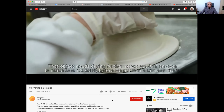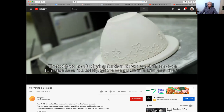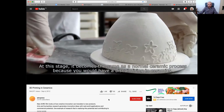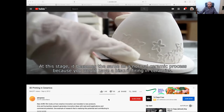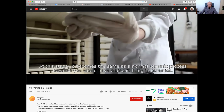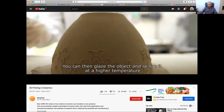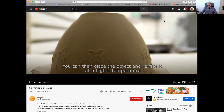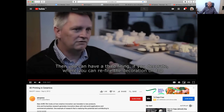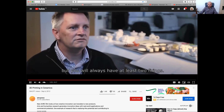That object needs drying further, so we put it in an oven to make sure it's really quite solid, before we then put it into a kiln and fire it. That's known as a biscuit firing, the first firing. And at this stage, that's where it becomes the same as a normal ceramic process, because you would have a biscuit firing in ceramics. So we biscuit fire it to a temperature and then take it out of there. You can then glaze the object and refire it at a higher temperature for the glaze to go over the ceramic object. And then you can have a third firing if you decorate, where you would refire the decoration on top. But you will always have at least two firings.